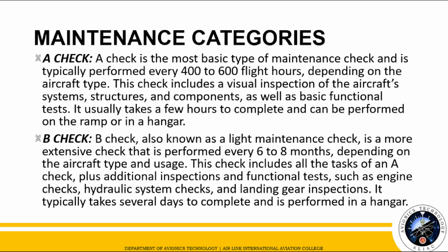The manpower needs here are 20 to 60 man hours. And A check also takes 200 to 300 cycles. One cycle means takeoff and landing.